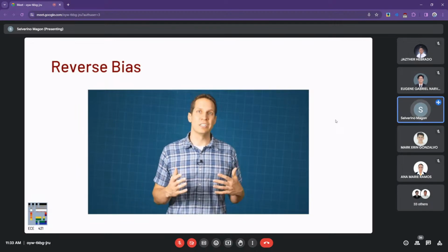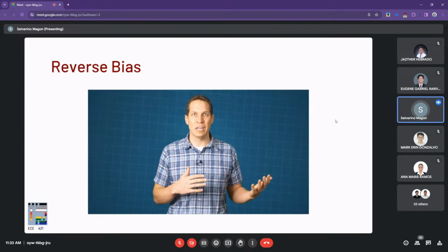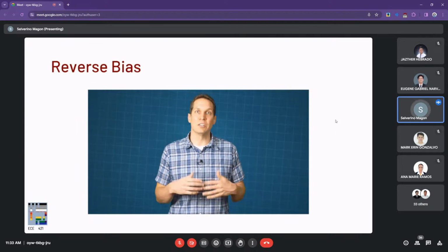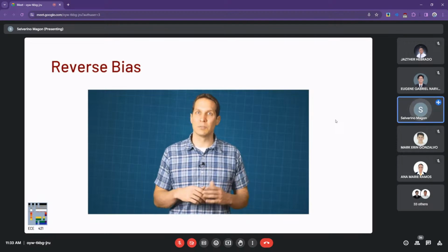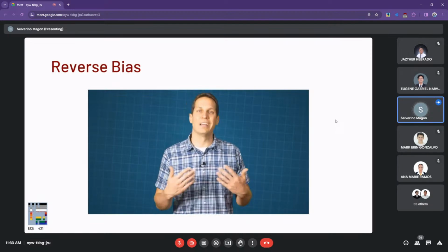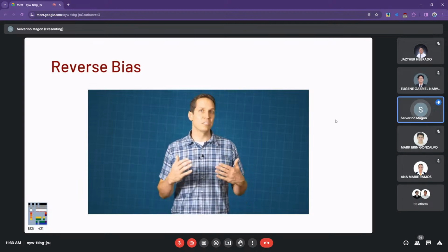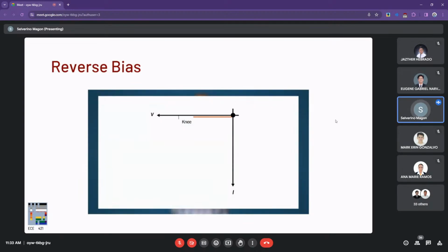They are also high in energy, and so they repeat the process of colliding with atoms, which results in multiplication of conduction electrons. Because these electrons possess high energy, after they cross the depletion region, they don't combine with the minority holes, but go through the N region as conduction electrons. The multiplication of conduction electrons causes the reverse current to increase drastically. If the reverse current is not limited, this might cause damage to the diode.